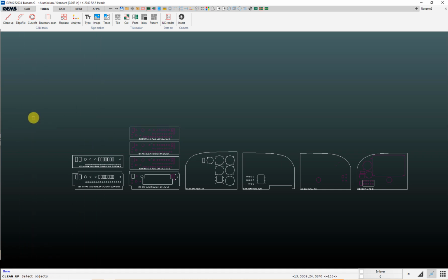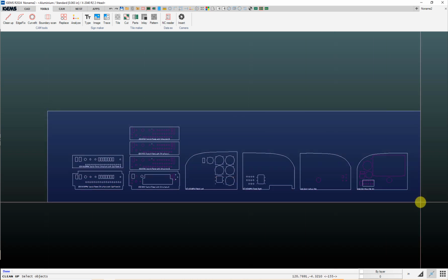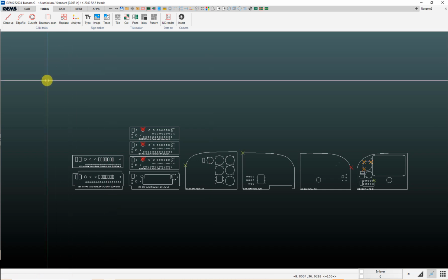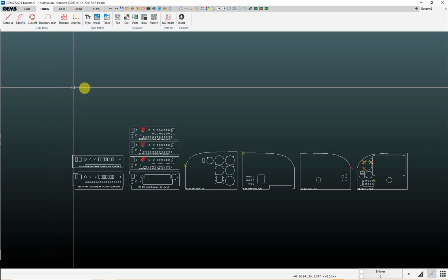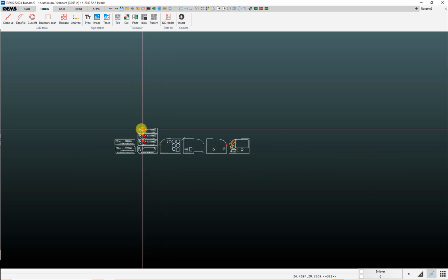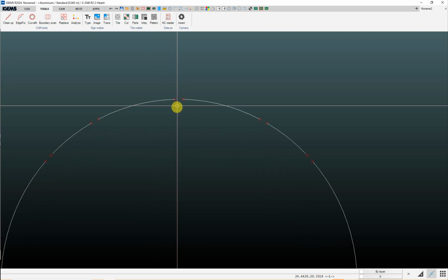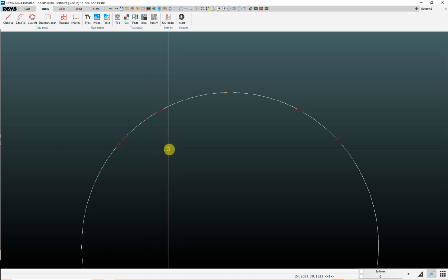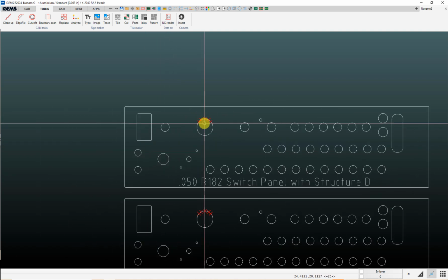We'll just hit enter, left click, drag a box around here, left click, enter, and down here in the bottom it shows us 1123 entities before, 909 after. If we click on the Analyze button again, we'll see that we have far fewer red and yellow X's. Now would probably be a good time to zoom in on some of these and see if we need to clean things up further. If I zoom in here, it looks like they want to do stitch cutting around here to leave this knockout. We'll leave that the way it is.